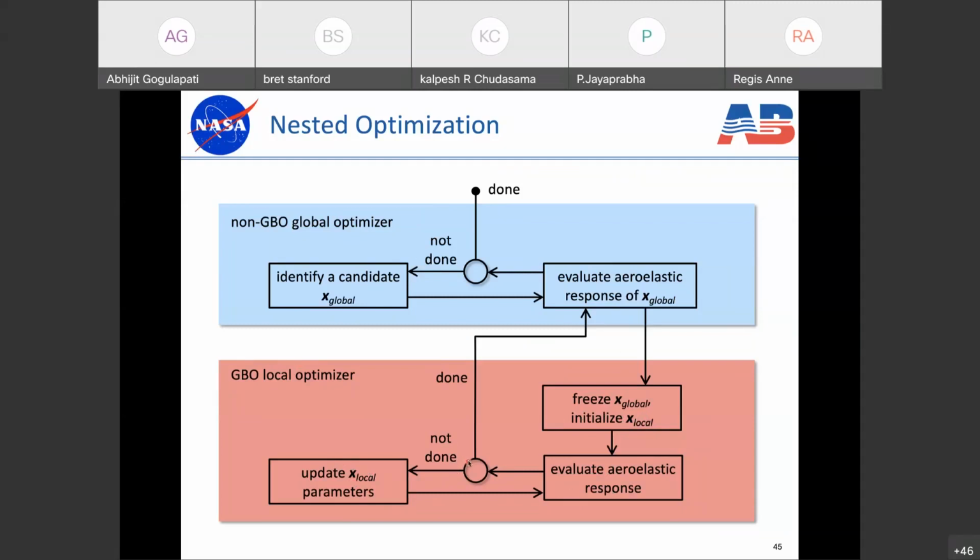And once this is finished, we pop back up to the outer level. We provide the final objective function to this result here, and then we do this again. So this is extremely expensive, but it's really the only way we know of to handle simultaneous shape, sizing, and topology when those topology design variables include integer design variables.